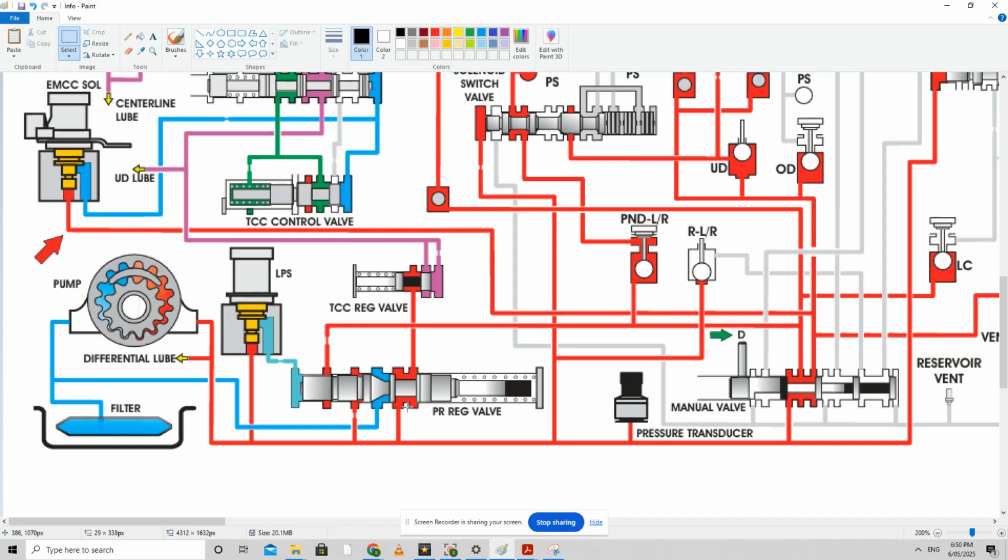This regulates the line pressure. And then we have the line pressure solenoid itself. We will go into the construction of this line pressure solenoid later on, but it usually has these two openings, one at the top and one at the side. They receive the same line pressure. So if it is receiving pressure from here, it has to bleed some of the pressure from the side to reduce it. And this is what it usually will do.